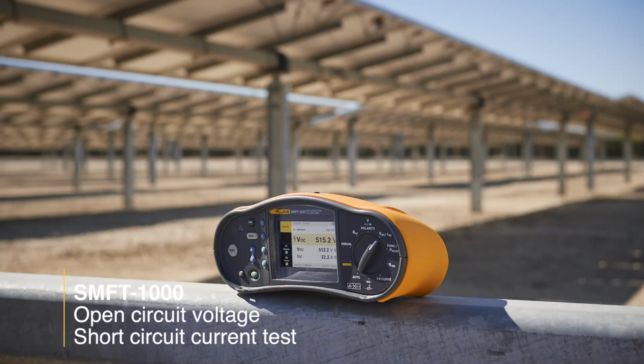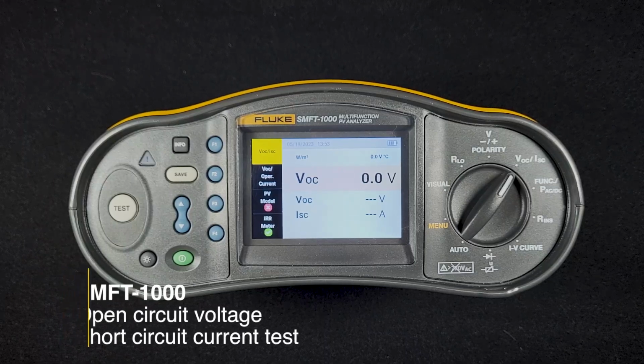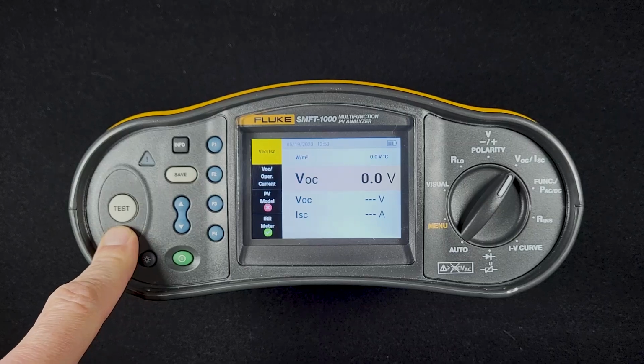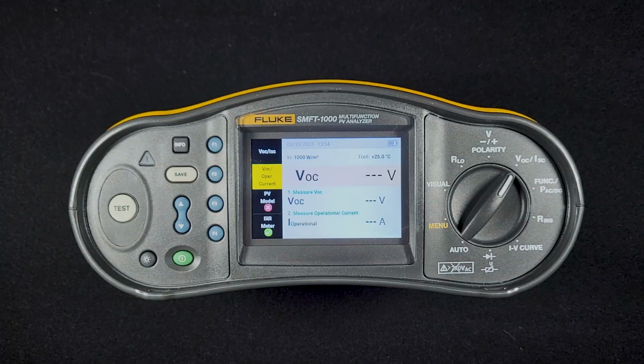We're going to look at the open circuit voltage and short circuit current test of the SMFT-1000. Here we can see the screen that we get when we switch to the VOC-ISC test. If this were hooked up to a module or a string of modules, we'd be seeing the open circuit voltage here. If we had the short circuit current, we could run that as well. We would need to hit the test button to see the short circuit current. We can also test operating current and operating voltage.